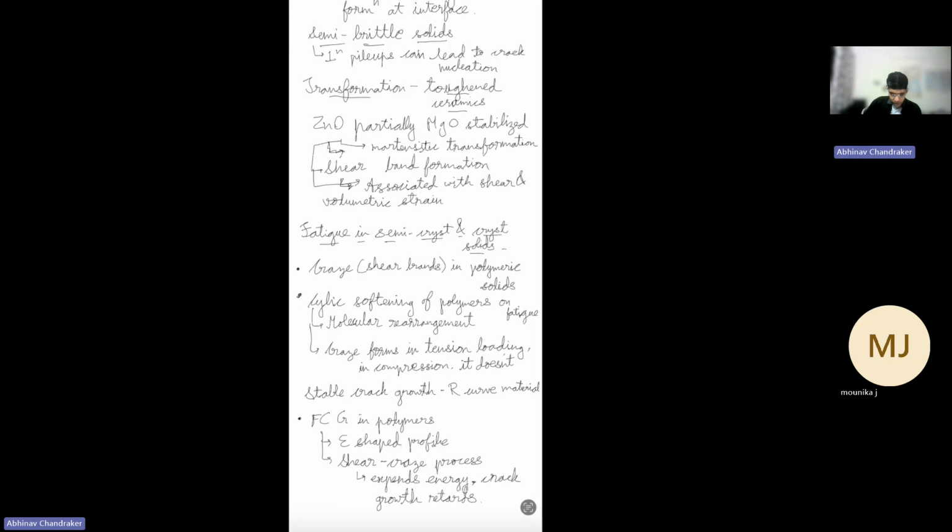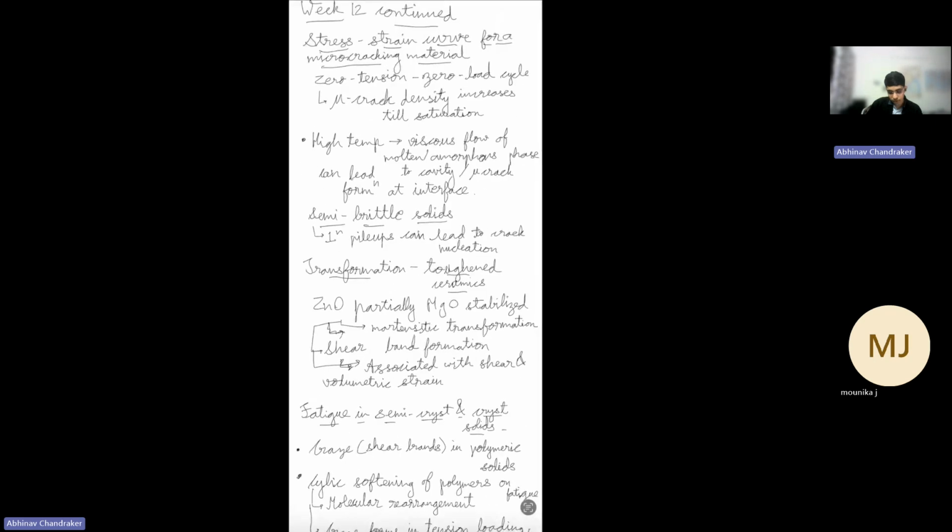Dislocation pileups are much easier in semi-brittle solids because their mobility is very low, and crack nucleation can occur as a result if the stress localization is too high. One way to combat this limitation of what we called brittle or semi-brittle solids, majorly ceramics, because ceramics have ionic bonds which can have these issues which we talked about and which have these mechanisms occurring.